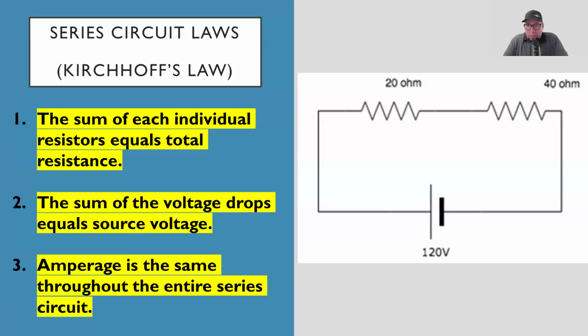And now if we measure amperage on the ground side of the circuit, so that's after the 40 ohm resistor, going back to ground, according to the law, we should also still measure 2 amps. And once this is true, if we were to set up a circuit of this nature on an electrical board and measure amperage with a digital multimeter, it would work. The math would work out. The numbers would work out.